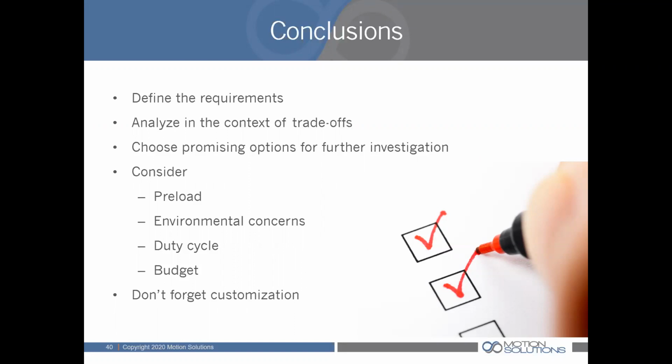We had rails in a robotic surgery application that were exposed, and the doctor or nurse would put a drape over, and what they found was the sharp corner of the rail was cutting the medical drape. So they actually asked the factory to make a rounded cross section of the rail to eliminate that sharp corner.